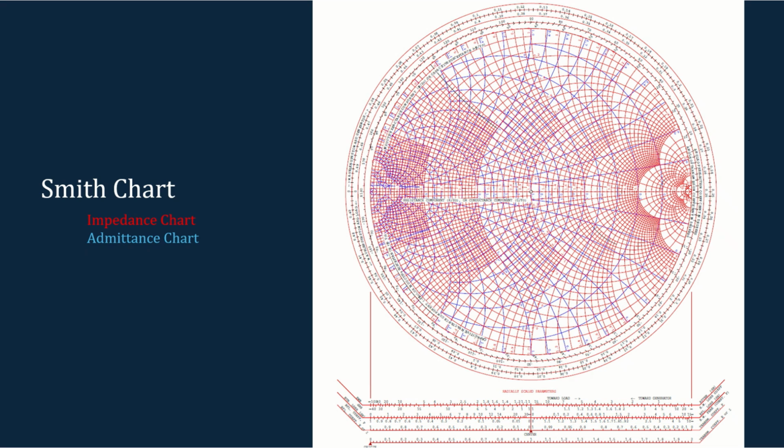While designing the matching circuit, we have to use inductance and capacitance, which can be in series or in parallel configurations. To find the equivalent impedance when adding a series inductance or capacitance to capacitive loads, we can use the complete Smith chart.